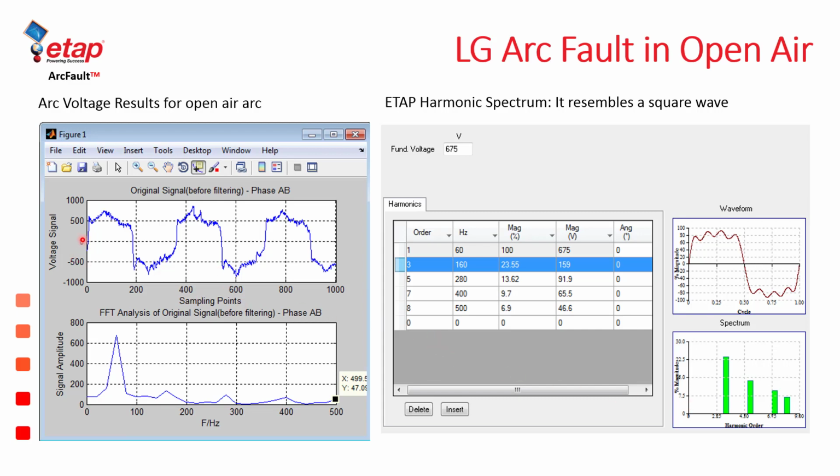Here we can observe the actual measurement, which represents a square wave with different levels of harmonic content. Once that measurement is sampled and processed through fast Fourier transform analysis, we can decompose it and obtain the different harmonic orders. Once we have the harmonic order information, we can develop root mean square, or RMS, equations to represent the arc voltage and current.